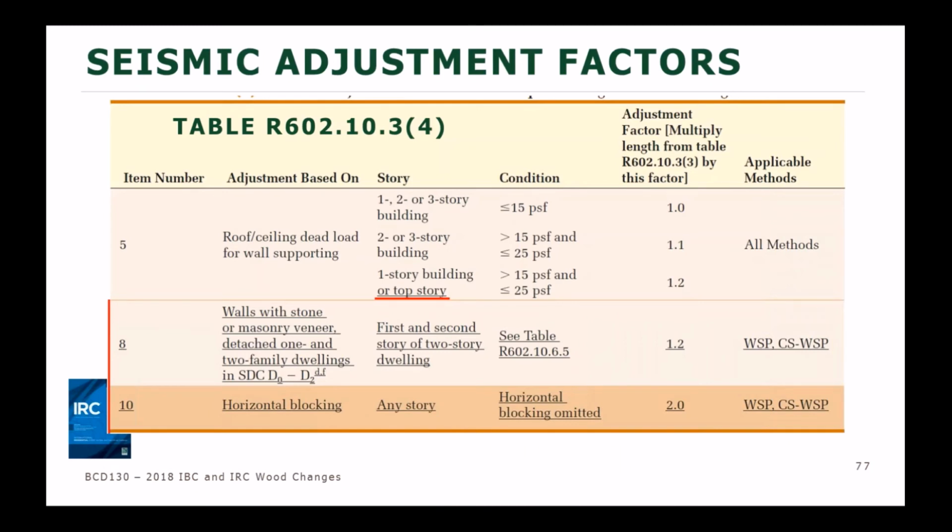And that 20% is going to go on the wall that has the brick veneer, and any perpendicular braced wall lines that run into it. So the exterior side walls, and if you have any interior braced wall lines that are running front to back in the building, then extra bracing would go on those as well. Now, unfortunately, since we don't have anything about increasing the amount of bracing on method gypsum board, those interior braced wall lines are going to end up being wood structural panel or continuous sheathing wood structural panel. But in high seismic regions, we're always seeing that have to happen when you're choosing to use the IRC and the wall bracing section. So that was the change there.